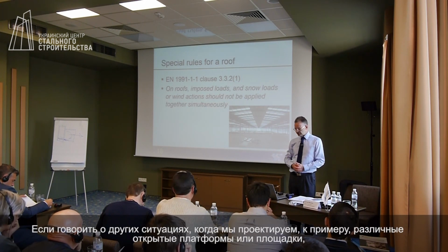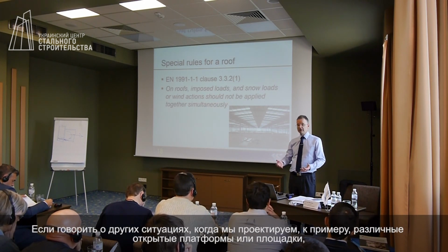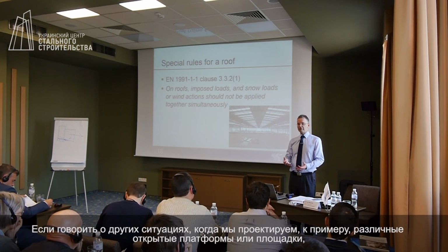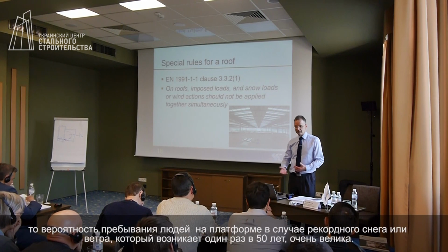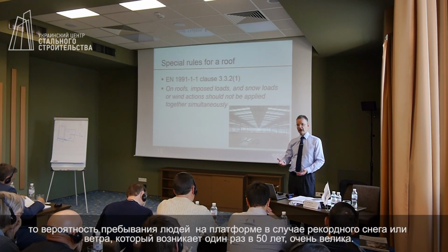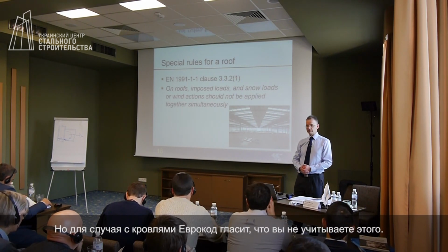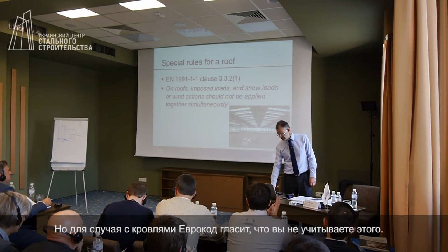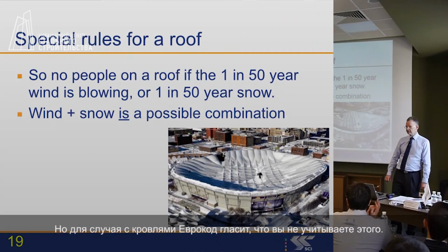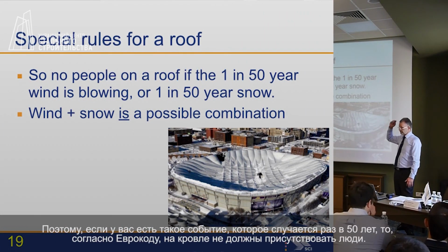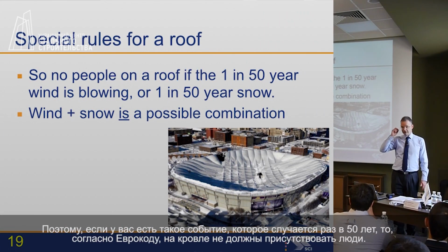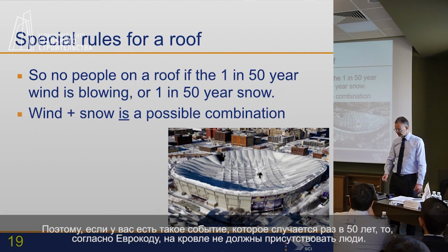Now, in other courses, people have said to me, well, actually I'm designing a platform for viewing the snow, in which case you would have people and snow at the same time. But for the ordinary case of a roof, the Eurocode says you don't consider it. So if you have this 1 in 50 year event, do you have people on the roof? Well, the Eurocode says generally not.